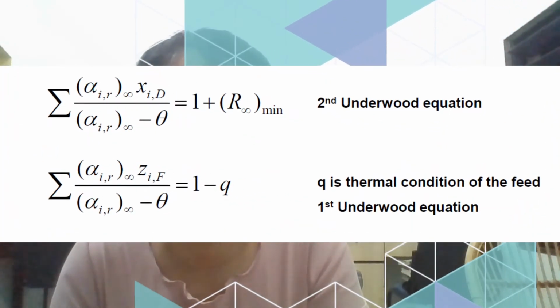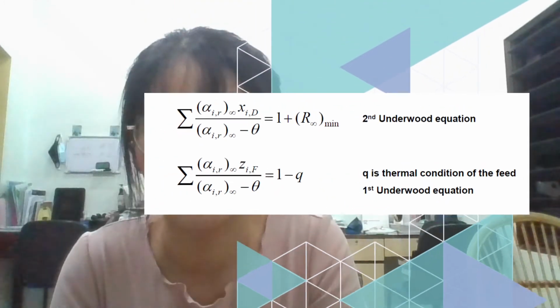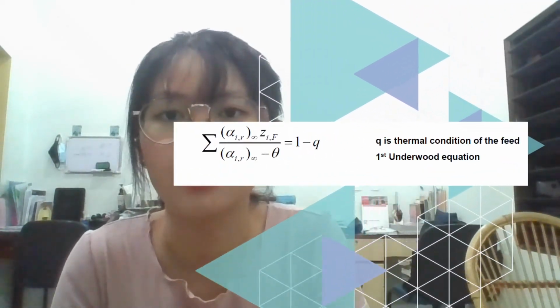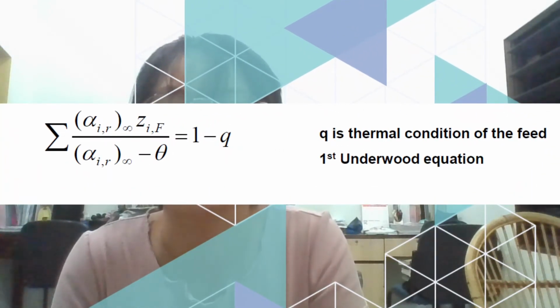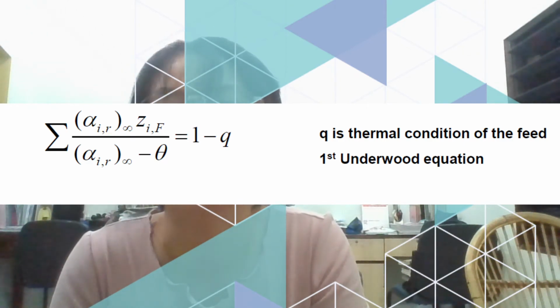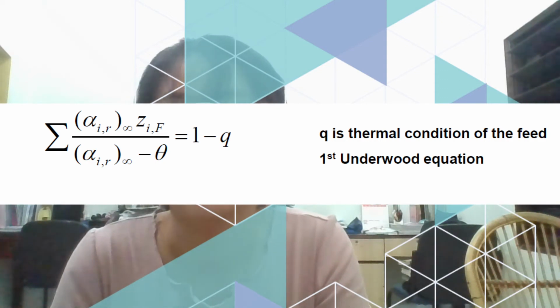Next, the Underwood equation is applied to calculate the minimum reflux ratio, R min. First, we use the Underwood equation to obtain the delta parameter value. Since only glycerol is in the liquid stage in the feed stream, the q value is 0.1153. The delta calculated is 0.1836.